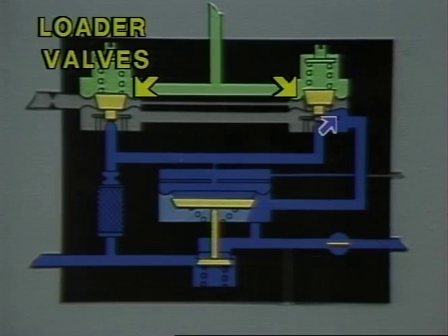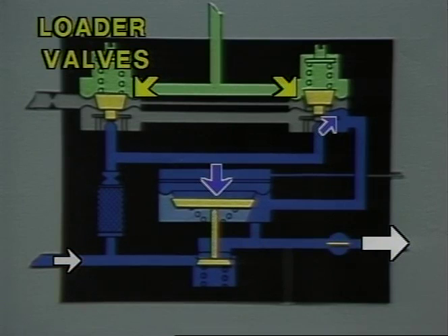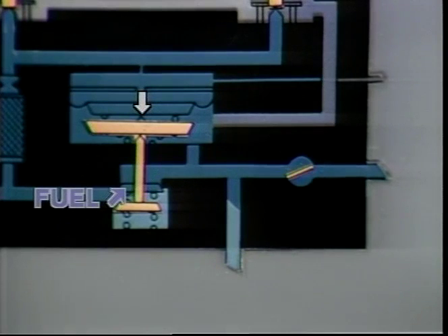what will be the control gas pressure on the opening side of the poppet, and finally, how much fuel will flow into the system. At 100% speed, the poppet valve moves to its null position. This action continues as a modulation function as the speed governor calls for control action and maintains engine speed.